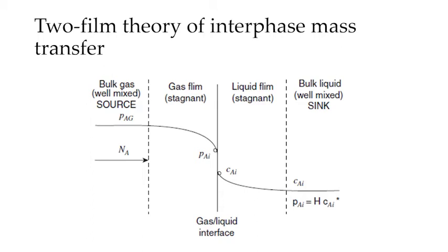That's because we are relying on diffusion to transfer a species from one point to the other. If you go past the boundary layers of both phases, we have here the bulk liquid and the bulk gas. In both of the bulk phases, we are assuming that convective mass transfer accounts for a large part of the mass transfer.